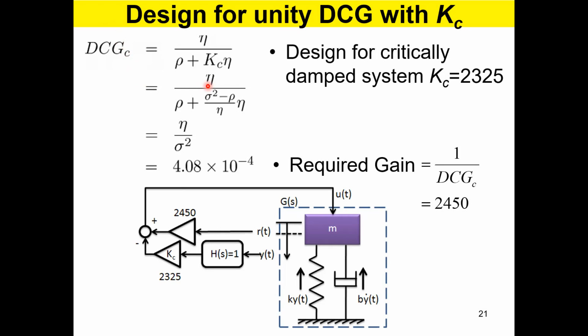Once we decide we want a critically damped system or a slight oscillation or overdamped, we have to first get that shape, the nature of the response. And after that, you can amplify it by a factor of 2, 3, 4, half, whatever, by adjusting the DC gain. Understand?